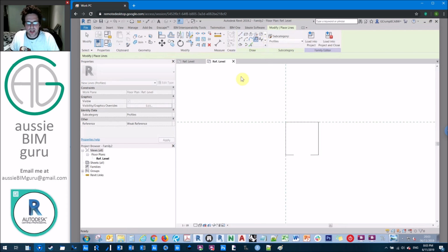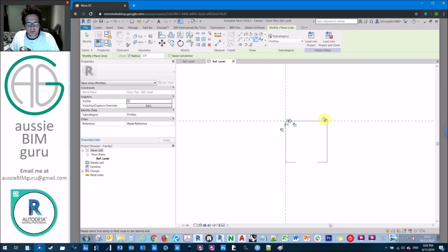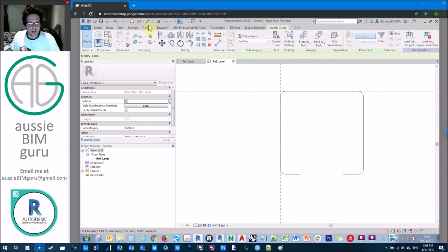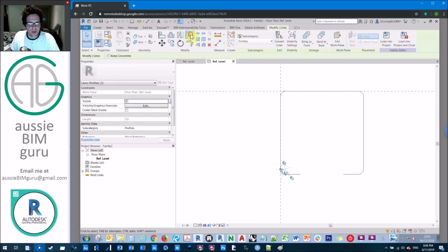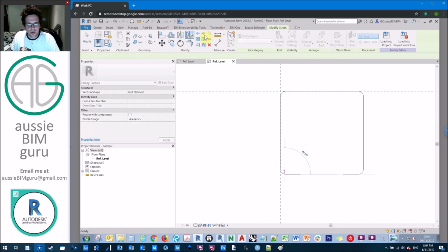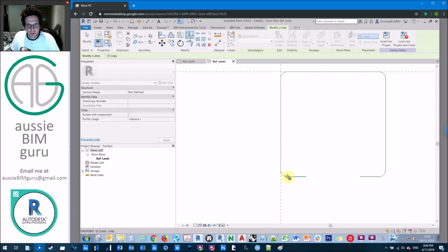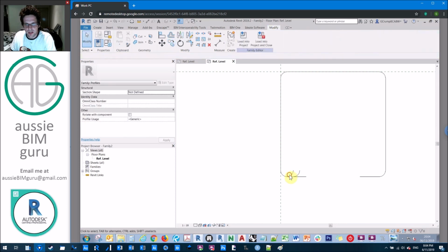And then we want to apply a radius to some of these corners. So let's just apply a radius of, let's say, 2.5mm. And I'm using this tangent arc tool, or fillet arc tool, sorry, which can be really handy for really quickly drawing tangent arcs. What I might do then is just mirror these. So I'll just mirror this one upon its center point. What I might do is just mirror and then move it across. So I'm going to mirror it upon this snap point, then make a copy and move that over 2.5 and delete the original.